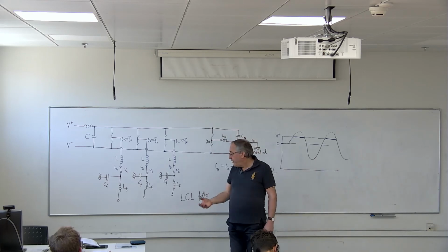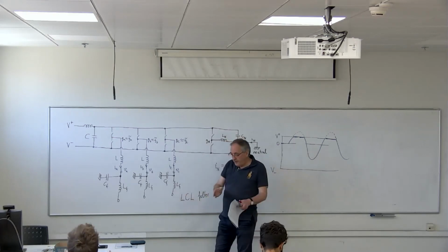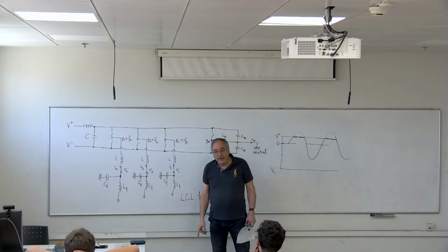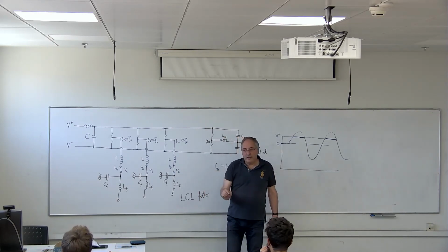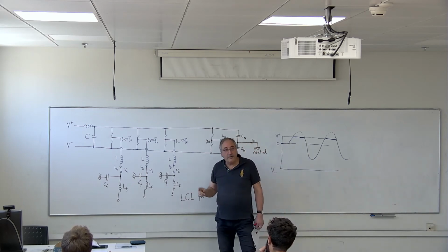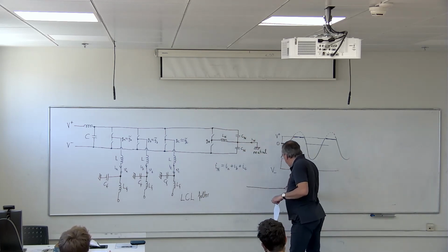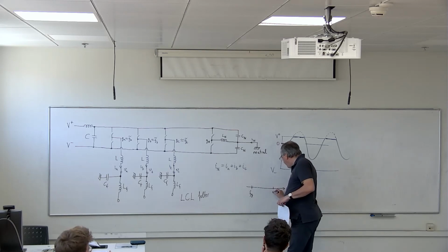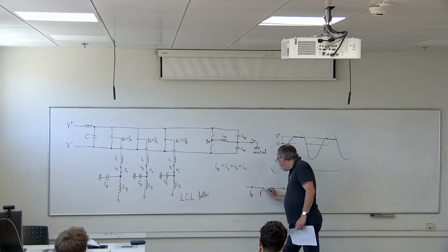So, for example, if you want to obtain 50 Hertz and your switching frequency is 10 kilohertz, then you take these two frequencies on a logarithmic scale, 50 Hertz and 10,000 Hertz, and you put the resonant frequency of the filter in the middle, but in the middle on a logarithmic scale. What does it mean? The middle between 2 points on a logarithmic scale. You have the frequency of interest, let's say the grid frequency, and the switching frequency, and you want the midpoint between the two, then that is the square root of FG times Fs. Think about it.